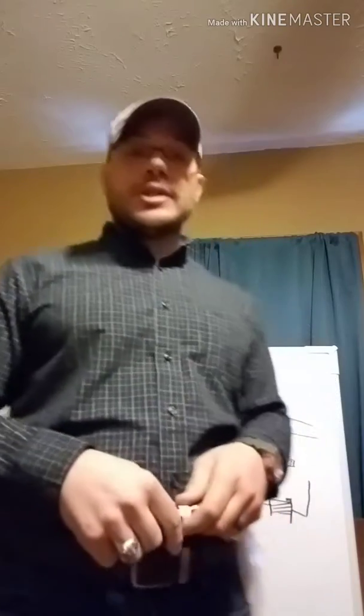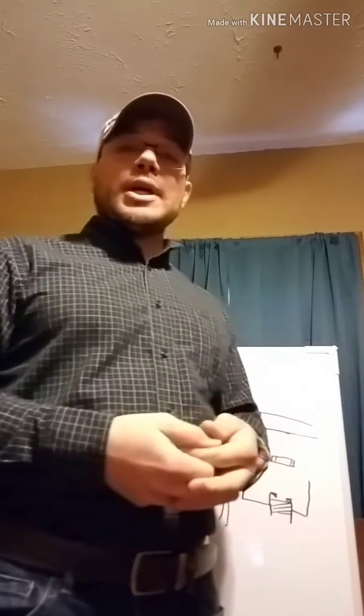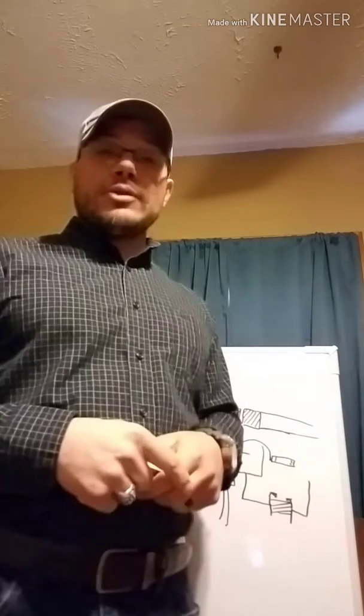342.100, construction. It says it shall be made out of steel with protective coatings or stainless steel. Okay. Now, most of the time, I believe that steel with a protective coating is cheaper than stainless steel, and so a lot of times that's what they'll do. They'll actually have protective coating on your steel, or you can use stainless steel obviously without protective coating because it's not going to corrode like regular steel is.